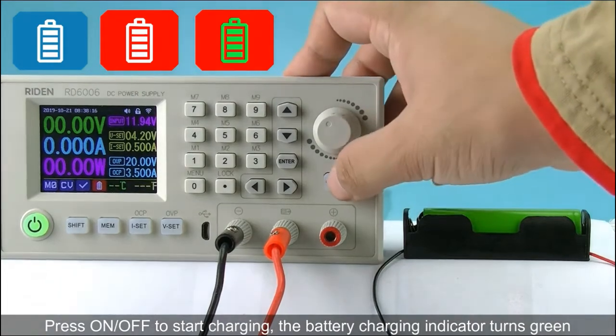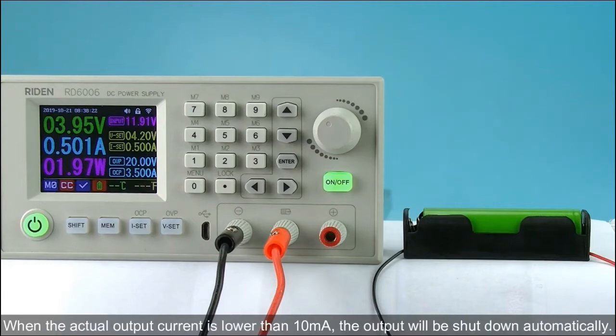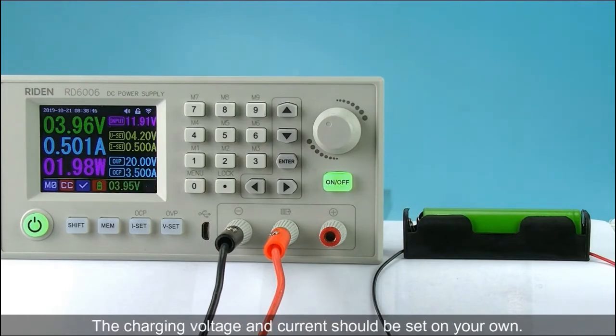Press on/off to start charging. The battery charging indicator turns green. When the actual output current is lower than 10 mA, the output will be shut down automatically. Battery with protection board may not be charged. The charging voltage and current should be set on your own.